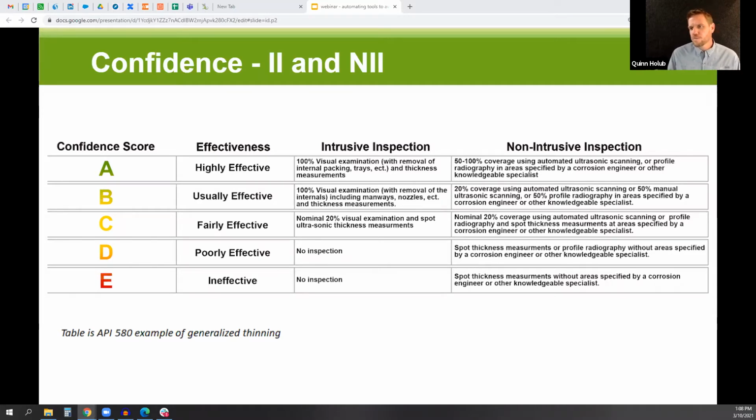RBI requirements for inspection coverage, like wall loss area and weld seam length, depend on the level of confidence that the inspection will find the potential damage. For example, some of the challenges are any actual corrosion has varying depth across the surface, and any weld seam flaw could be distributed randomly along the seam. But by focusing on the likeliest damage zones, the inspection confidence will be greatly increased.